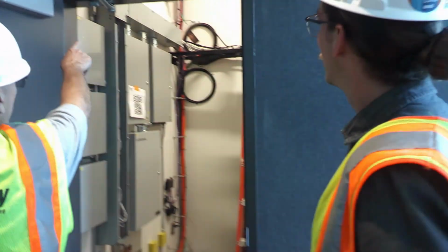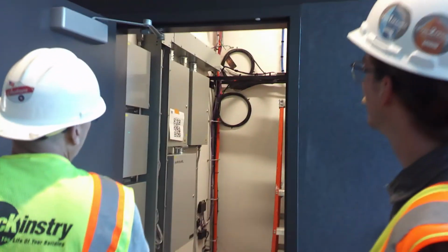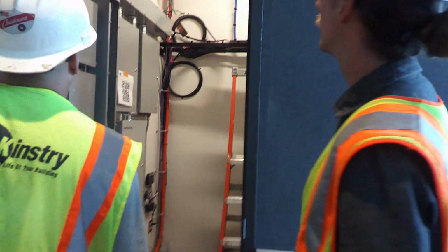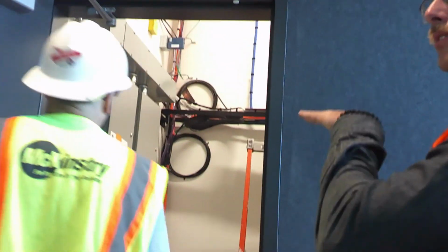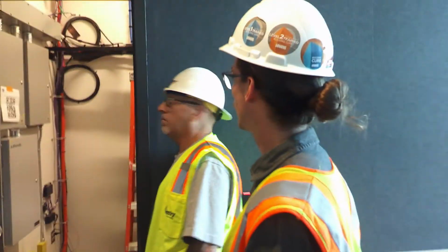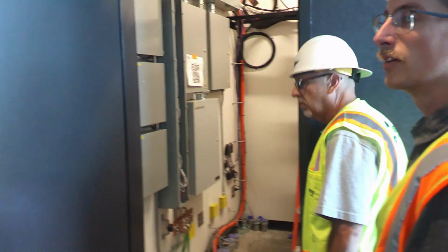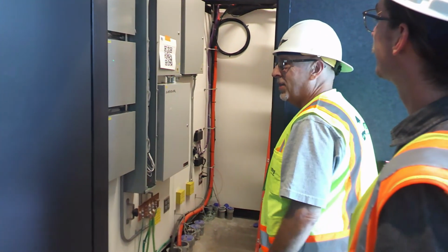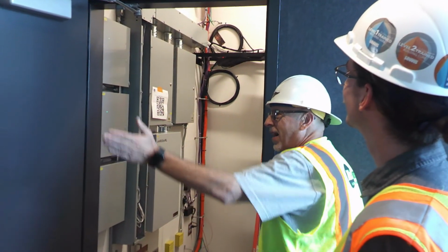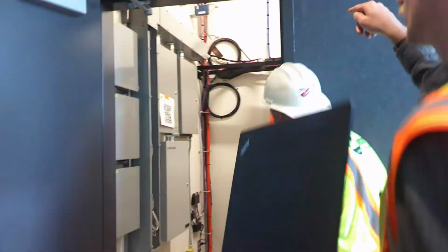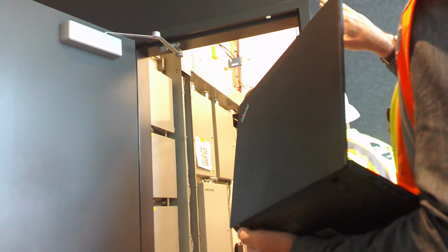That ain't you up there, is it? What is that? That's a bridge. Oh, that's one of us? Yep. I believe that's being used for one of the exterior room controllers. That's switching some exterior lights, so that'll be under the Sector F exterior zone. Right there, Alex. Sticking out like a flag, waving at you when you walk in. And the quick way to tell that's a bridge is one, it's blue, and two, it's only got 3 ports instead of 4.